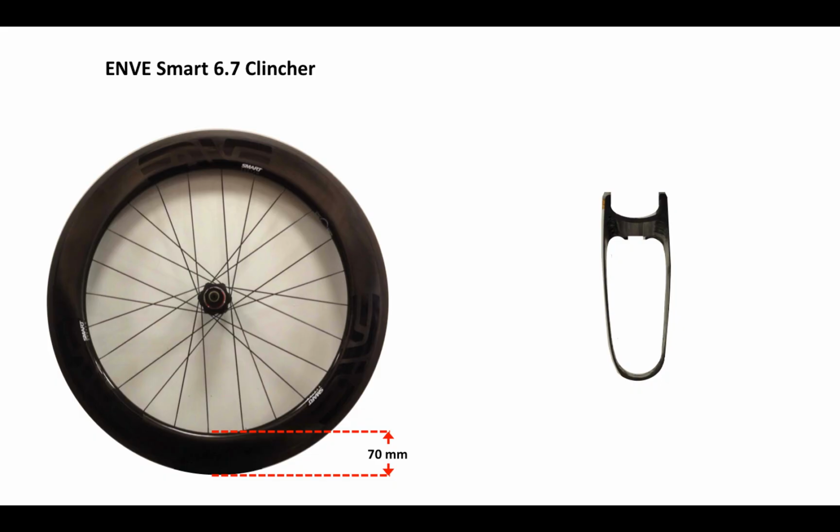This is a photo I took with my camera of the cross-section of the rim. Down here, the rim is 2.2 millimeters thick, 0.66 at this point on the side, 0.65 here, 0.53 here, 2.4 millimeters here, and 1.7 here. If the 1.7 looks like it's more than that, it's because of my camera angle.